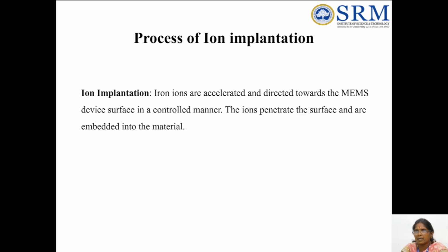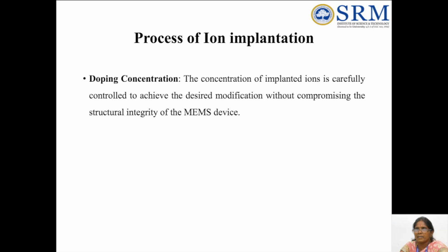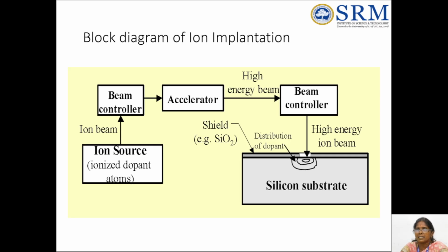Next, ion implantation. Ions are accelerated and directed towards the MEMS device surface in a controlled manner. The ions penetrate the surface and embed into the material. Next, the doping concentration of the ion implantation. The concentration of implanted ions is carefully controlled to achieve the desired modification without compromising the structural integrity of the MEMS devices. This is a major block diagram for the ion implantation.